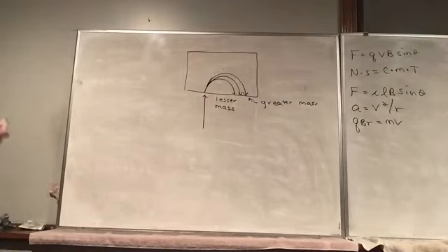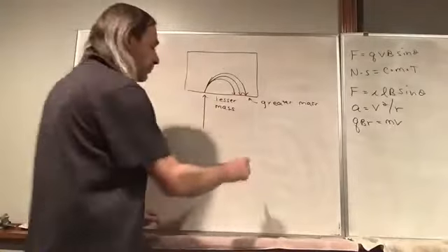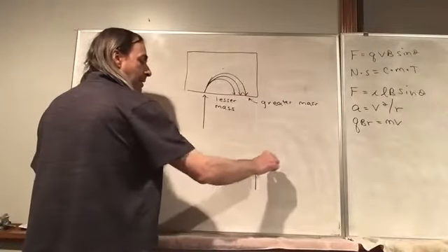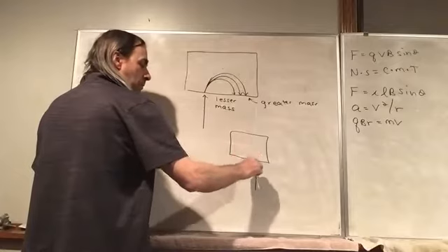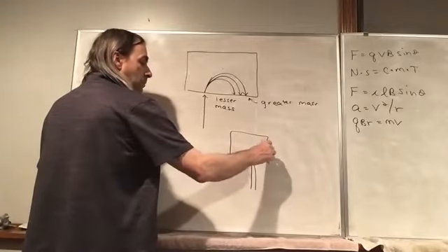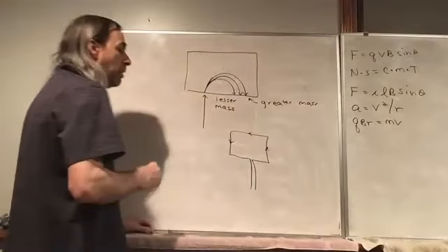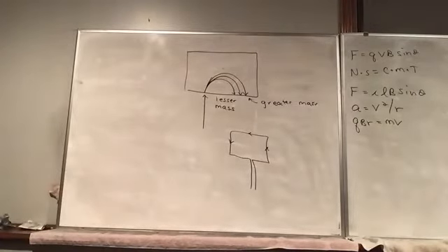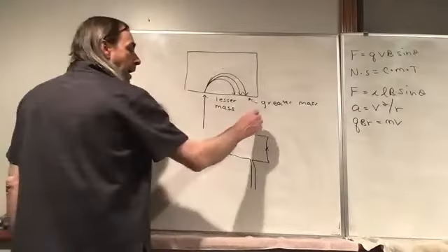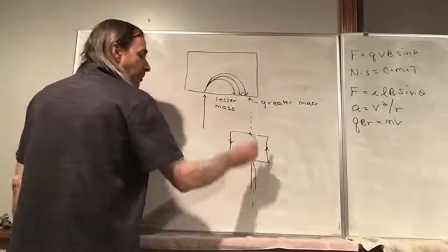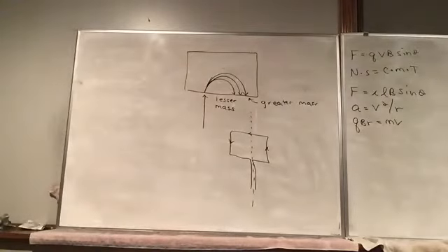So we have a force on a wire. If you make a rectangular wire, which you wouldn't really do, but it's easier for the purpose of calculation to consider a rectangle, and say this is in a magnetic field. So there's going to be a force on these wires, and that can cause rotation. We can cause this coil to rotate. So there'll be a torque on this coil.